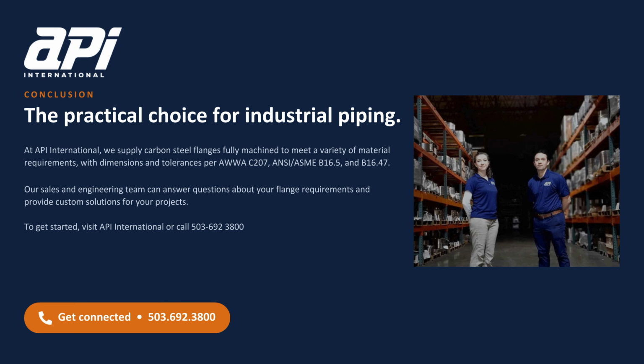In short, carbon steel flanges are the practical choice for most industrial and municipal piping needs. They are strong enough for pressure-rated use, easy to fabricate, domestically available, and cost-effective at scale. At API International, we supply carbon steel flanges fully machined to meet a variety of material requirements, with dimensions and tolerances per AWWA C207, ANSI/ASME B16.5, and B16.47.